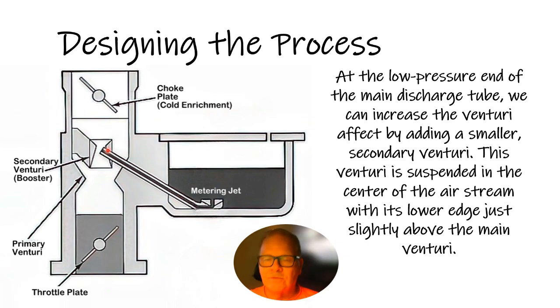That's a really good way to show one of the basic principles of how a carburetor works. There's a metering jet. This is really important. The size of that hole matters. I've actually had several different size jets in my toolbox. When I was working on Motorcraft 2150 carburetors, sometimes I would change the size of those jets to combat little drivability problems and stuff like that.